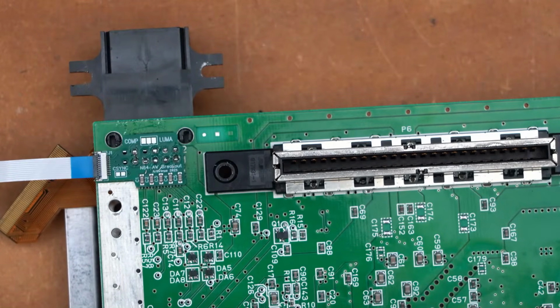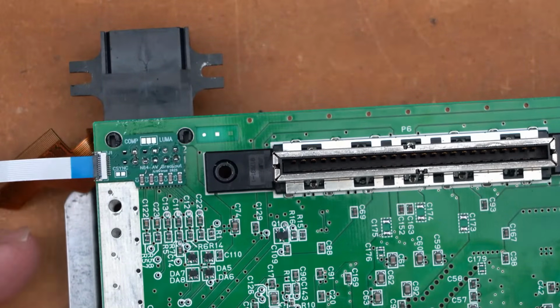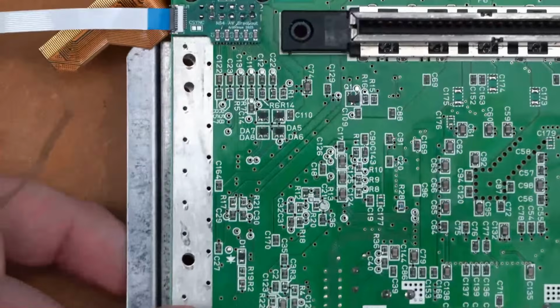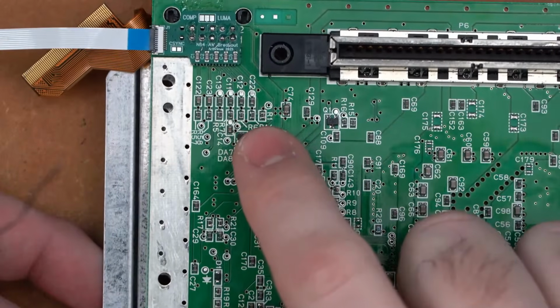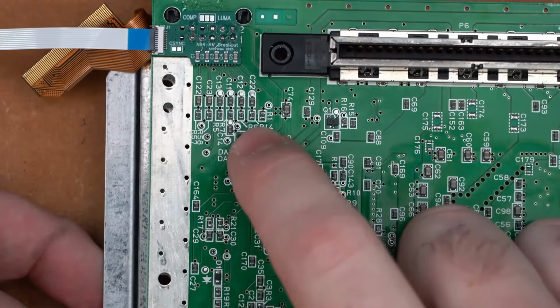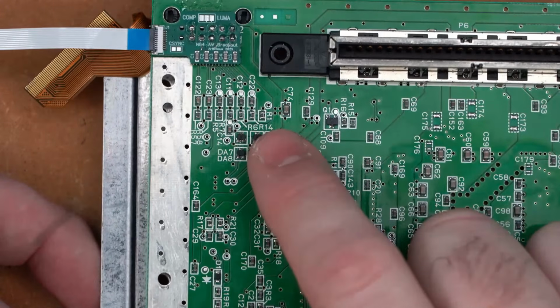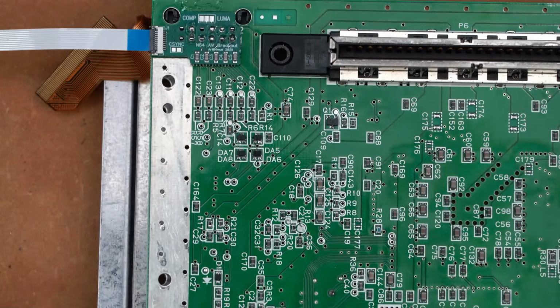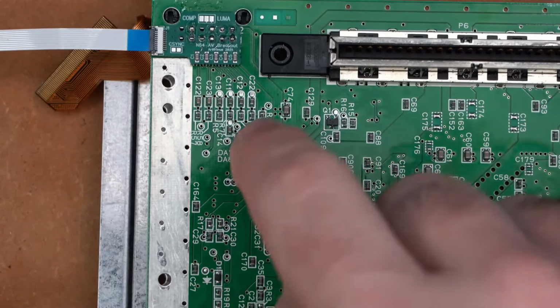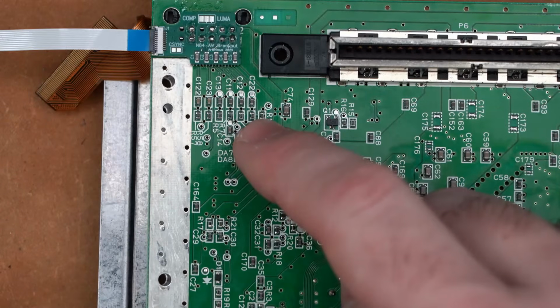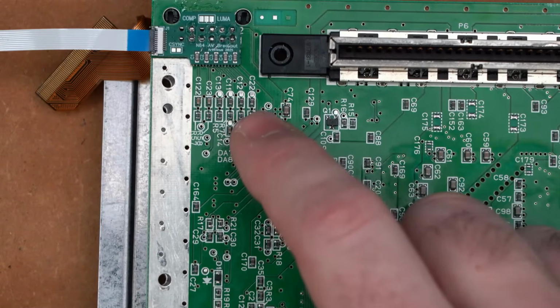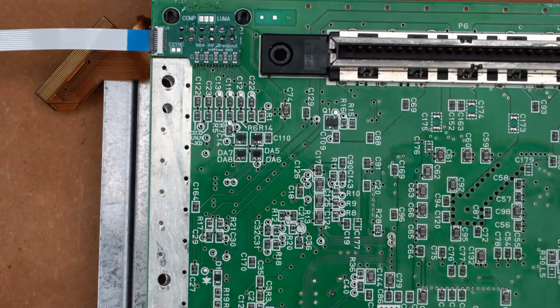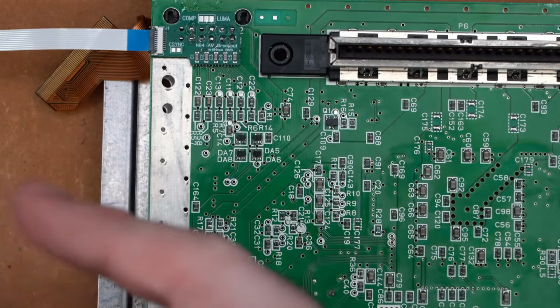So on these early N64 motherboards, they're going to have, let's see, C22, R1, and R14 are usually going to be populated on these early, like CPU 01, CPU 02, possibly CPU 03, I can't remember. Definitely not CPU 04. But these early ones, they're going to have these resistors and capacitors populated. Those are for C-Sync. The early boards, even though they didn't actually have RGB, they did have C-Sync wired up.